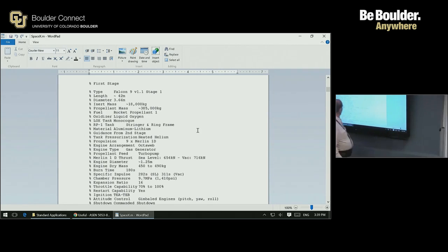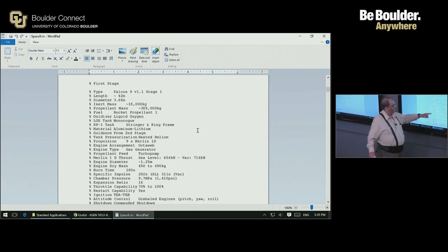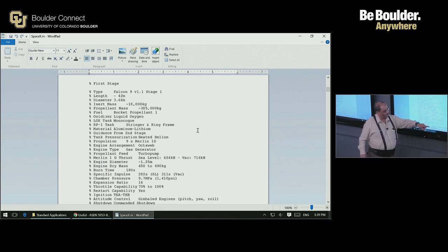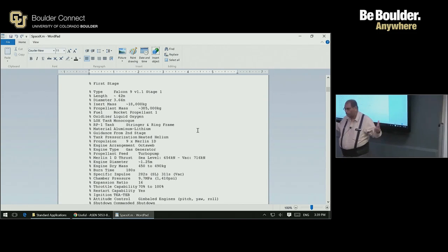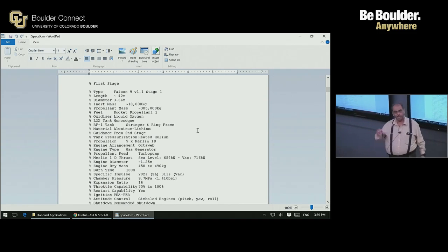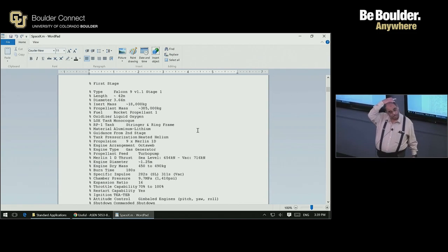Okay, this is mass. The dry mass is 450 kilograms, but when you compute the thrust, you have to multiply it by G naught to get the weight. And the thrust weight ratio, higher the better, because that is a good engine. Right now, Merlin 1D, I think, has the highest thrust weight ratio. It beat the NK-33, the Russian engine, which had a thrust weight ratio of 137. Okay, that's an achievement, really.